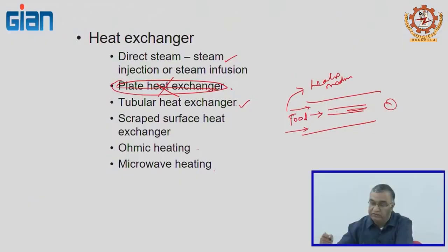Why are we doing that? For example, when you process protein products, maybe starches and so on, when you are heating them, the material can deposit and form what they call biofilm or something along those lines, and they can reduce the heat transfer efficiency. So, to facilitate removing some of those deposits and also facilitate mixing, you normally use this rotating mechanism.